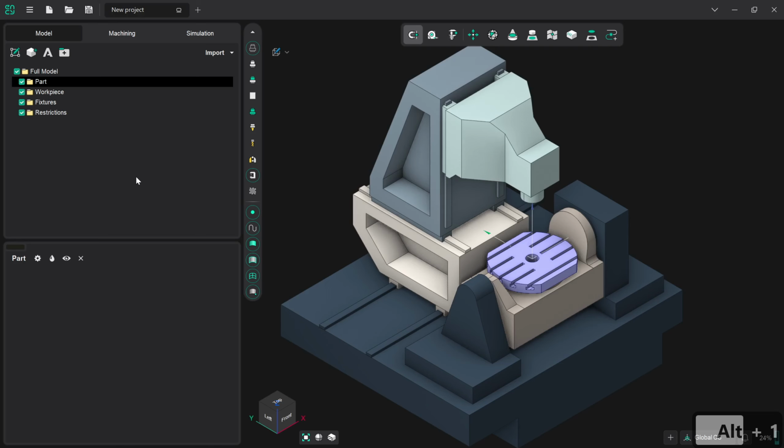Hi there. So we're going to go quickly through the process of importing a pre-made model into ENCY. Now ENCY can support pretty much all of the standard CAD formats. For the sake of actual 3D parts though, we needed to either be something based on the Parasolid kernel or a surface model such as IGES or 3DM. Or a mesh model, although obviously with mesh models you won't have the same degree of control that you get with more standardized CAD models.